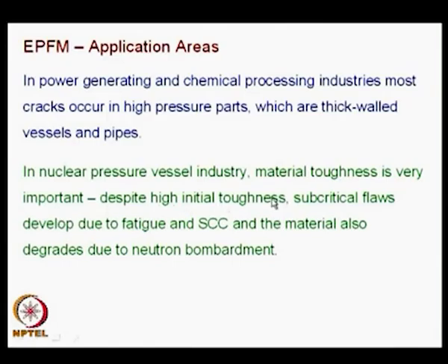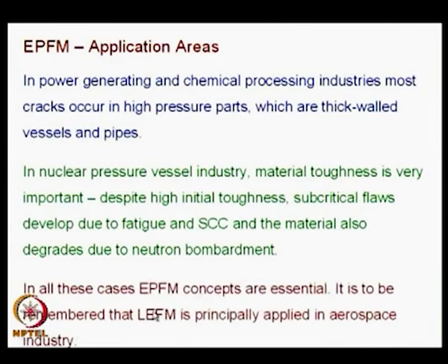Despite high initial toughness, subcritical flaws develop due to fatigue and stress corrosion cracking, and the material also degrades due to neutron bombardment. This is something peculiar to nuclear installations. In all those cases, EPFM concepts are essential.